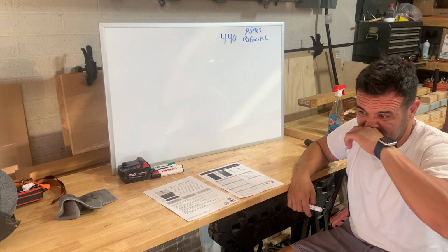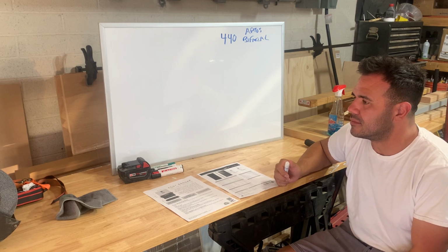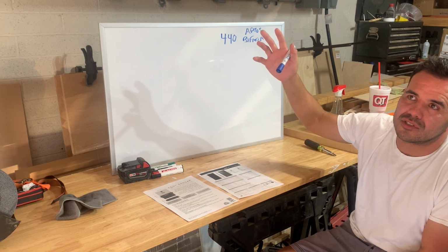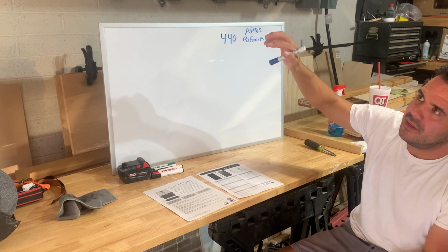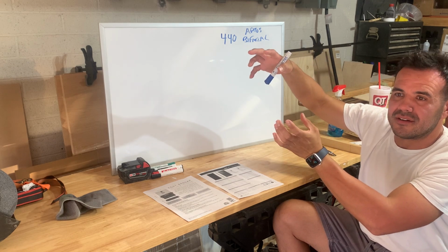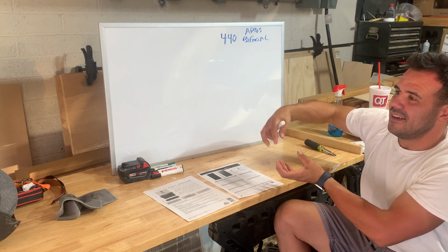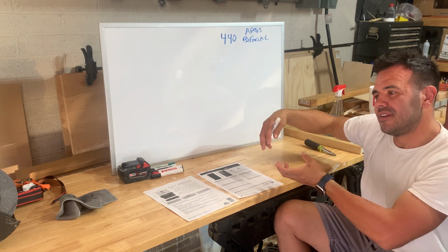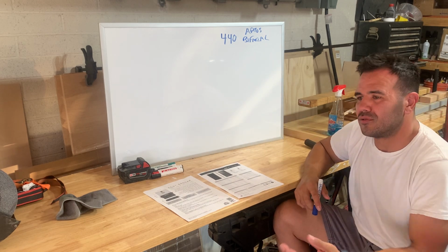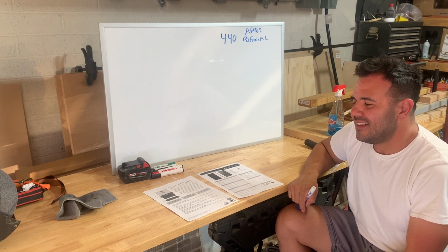So the more old school, I don't know if that's the right word, or traditional type of solar systems, you would usually have a solar charge controller, and that's going to have your MPPT or MPPTs in there, and then from there you would have another separate device, an inverter. Your charge controller would be hooked up to your inverter, and then your inverter converts your DC power to AC power, and then somewhere in there you also have a battery that's hooked up. That's more of a, I hate to say old school, but I don't know any other word for a more traditional type of solar system. That's not the solar that I'm familiar with.